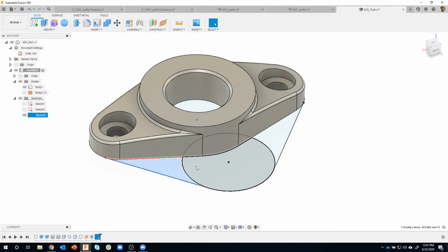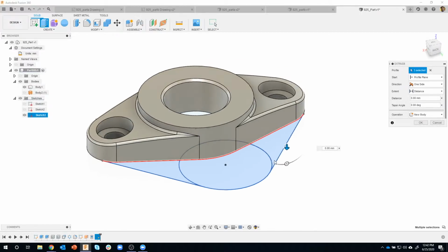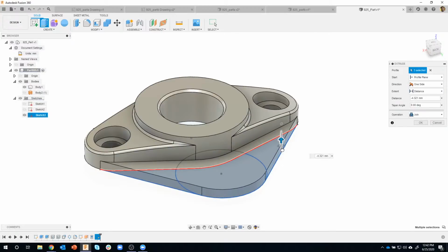And I'm going to select these three regions, right mouse click, and say extrude. You've seen me do this multiple times. I hardly ever go up to the menus. They're all usually in the right mouse click. It shows you the commands that make sense. So instead of having to figure out which command, I let Fusion show me which command. So I'm going to say extrude. I'm going to start to drag up.